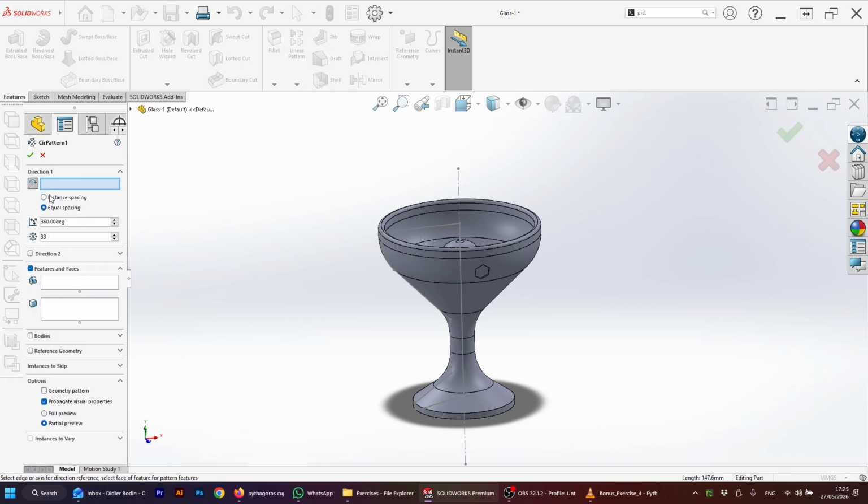In circular pattern, here he's asking me where is the axis. I can tell him here it is, and he's asking me what kind of bodies, but I can also tell him which features I want to duplicate. So in order to do that, you can see that now where I usually have my construction tree with the functions I did, it's being covered by something else.